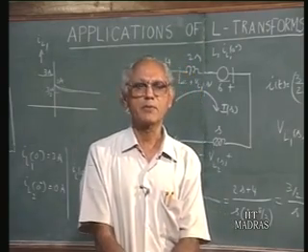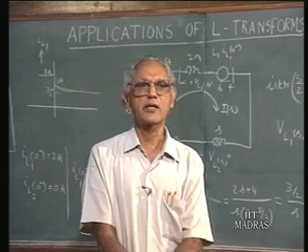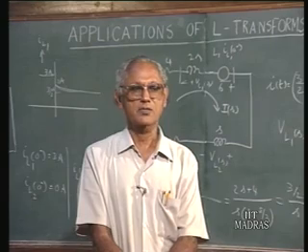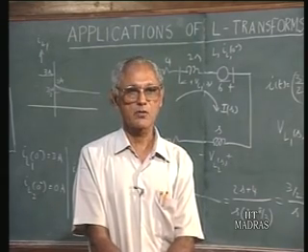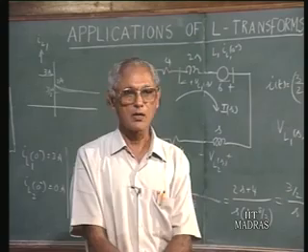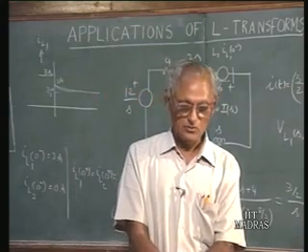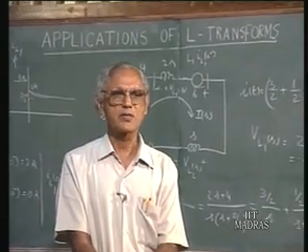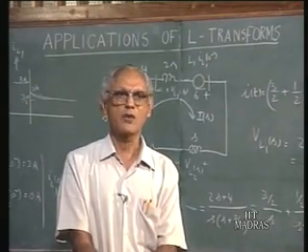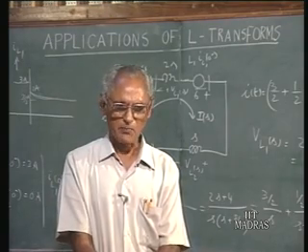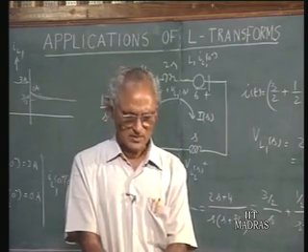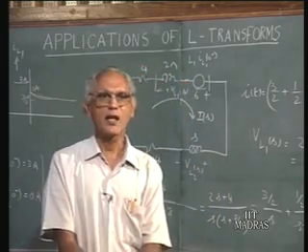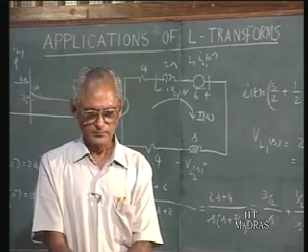So one should also know how to handle transient problems using the classical differential equation approach. Even though Laplace transform has a lot of advantages and we for the most part resort to Laplace transforms, one should not completely ignore or forget the differential equation approach to the solution of transient problems. Particularly in very simple cases, you can write down the differential equation solution by mere inspection. You do not have to transform those equations every time. So it's a powerful technique, no doubt, but in very simple cases the straightforward application of differential equations will fetch you the result quickly and also with a little bit of insight into the working of the problem.